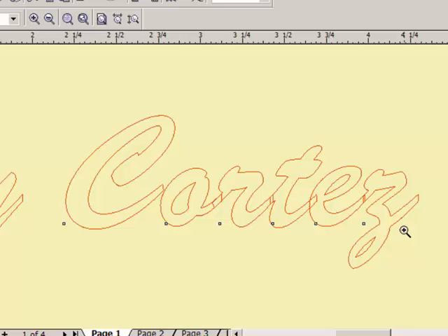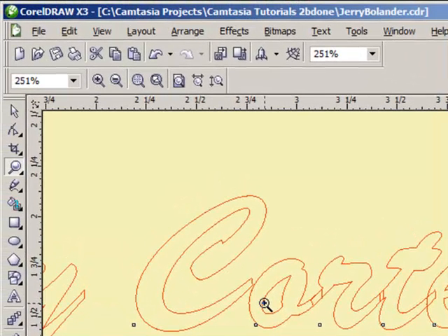You won't notice those overlaps. But when we're vector cutting something out, obviously, it will cut through each of those red lines, leaving not at all what we had in mind. So we'll need to weld that. But just before we do, I notice we don't have a connection between the C and the O. All the rest of the letters have a nice overlap.